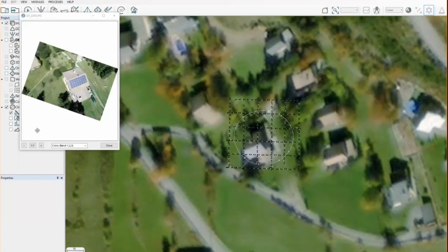I can show you here an example of the oblique imagery. We can see that the angle is not too far, so we're able to see the side of the building. Also, if you want better texture on the bottom side of the building, another ring at a lower altitude with a slightly higher camera angle could have been used, but it's a fairly good start if you want to integrate oblique and nadir imagery.